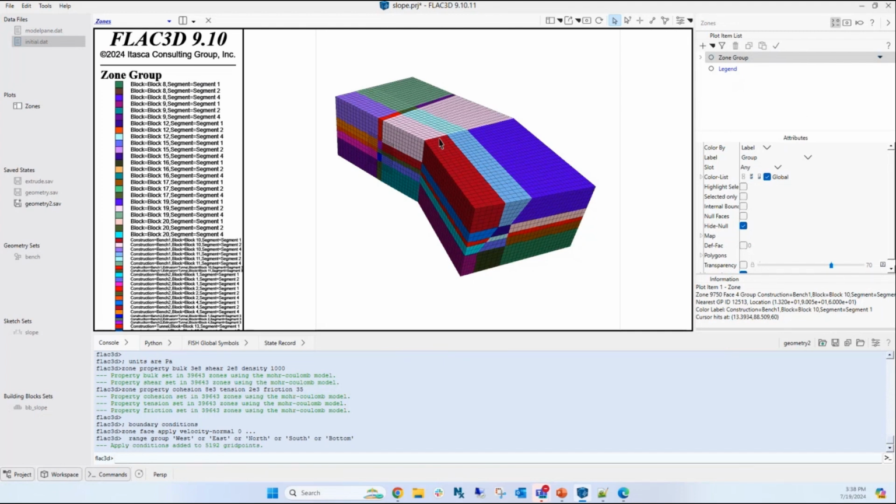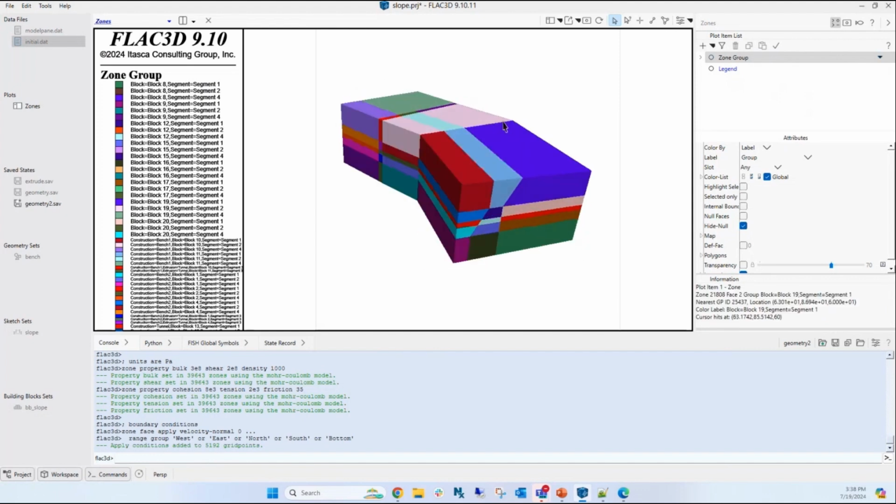You can't change the state of the model. You can plot things, and you can hide things in the plot, but it won't actually change the state of the model like the model pane does. And so the distinction is important. We want to be able to create these plots and not mess up the model. Anything that messes with the model is restricted to just the model pane. Otherwise, it gets super confusing because you have 10 plots open and you change one of them and it changes the model and then it breaks all the other plots and you've got a mess, right? So think of the model pane as a special plot that's interactive.